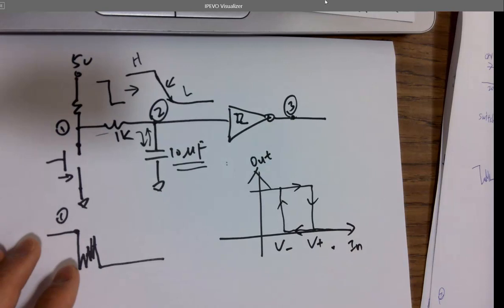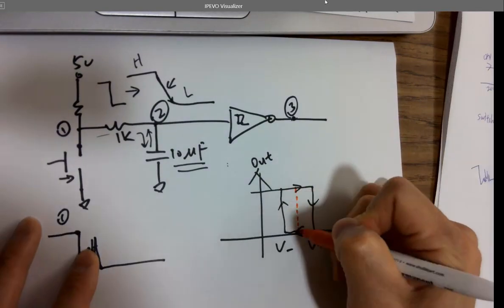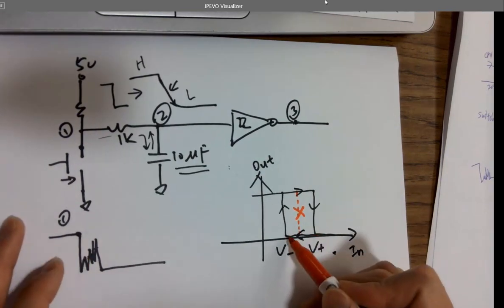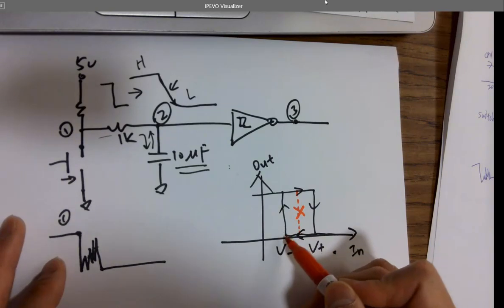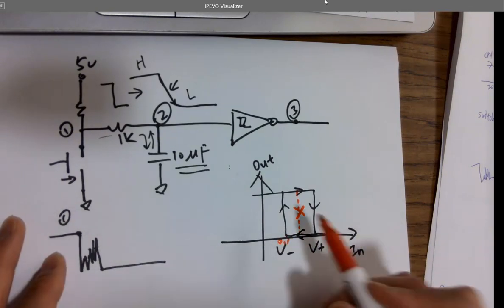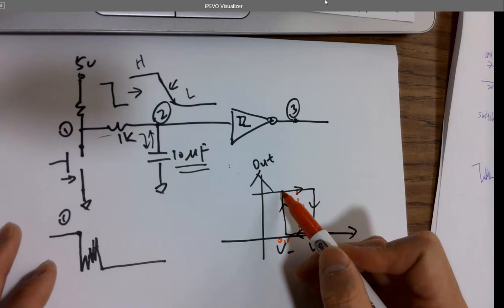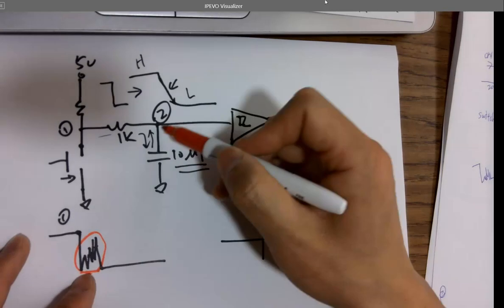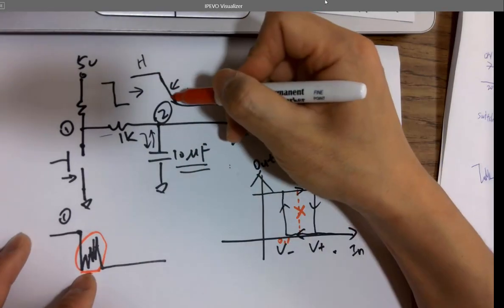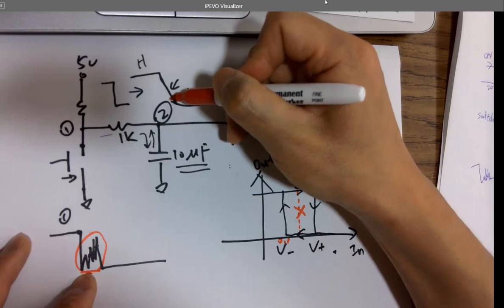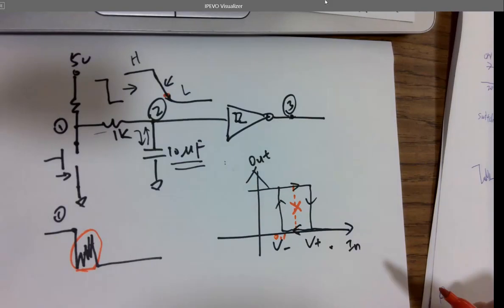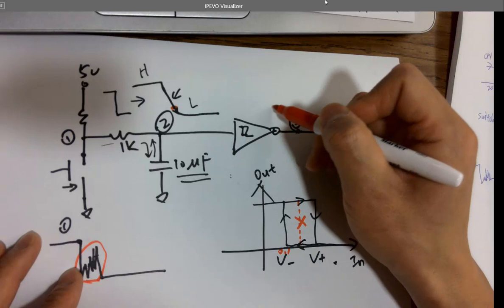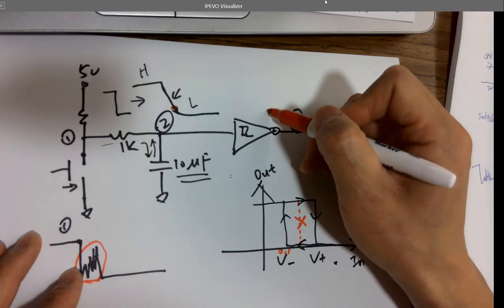So it's not like an inverter switching at 2.5 volts. It has to fall to some point. It's pretty close. I don't know what the voltage is, probably 0.1 volts or something, and then switch to high. So why does this help get rid of these things? Or probably this is already gone after the filter, okay? So whenever it's falling down, it only switches somewhere around here, okay? It's giving you a rising edge, which is a sharper rising edge.